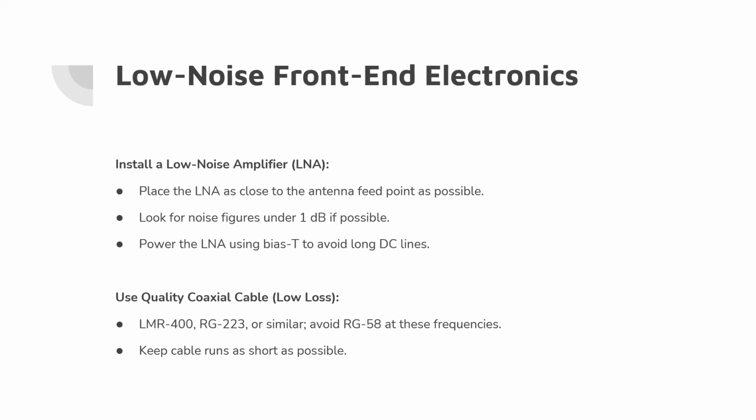Yeah, I would agree. I think cable is still important, even if the LNA is right at the dish. At 1420, you're still getting 1420 out of the LNA. If you had some kind of converter that would drop it down to a couple hundred megahertz or something, that might not be as much of a problem. But 1420 is still fairly high frequency for coax. RG58 would not be something you would want to use.